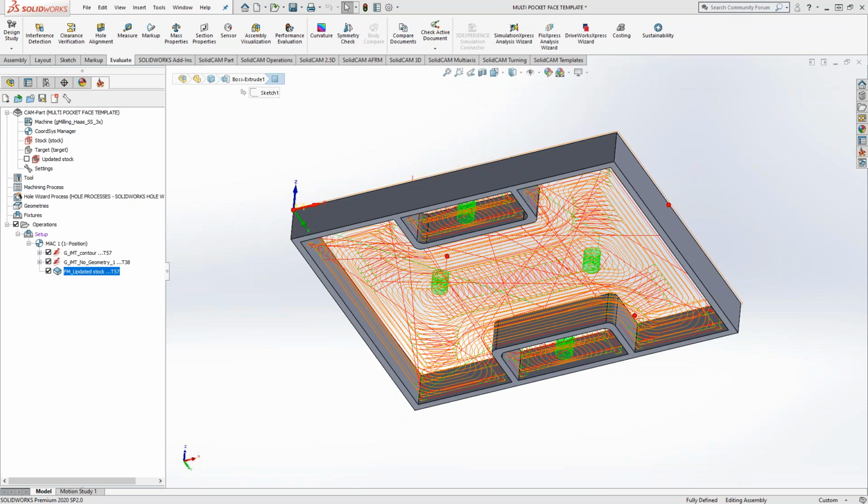That way, when you go to part 2, file 2, so a separate CAM part file, a different geometry completely, but you'd like to apply the same toolpath methodology, then you can load the template for Mac 1, the template for Mac 2, and as long as those apply to your Mac 1, Mac 2 in your second part, you've retained all that intent. You've brought in your tools, you've brought in your toolpaths, synchronize and calculate, or select geometries. So you can grab that information and bring it over.